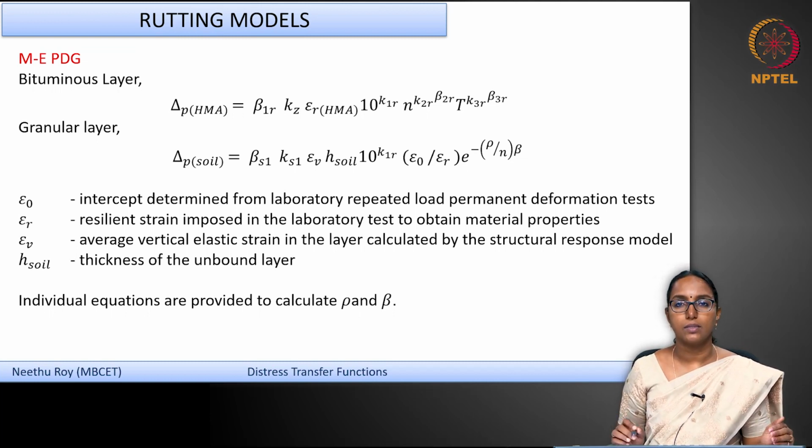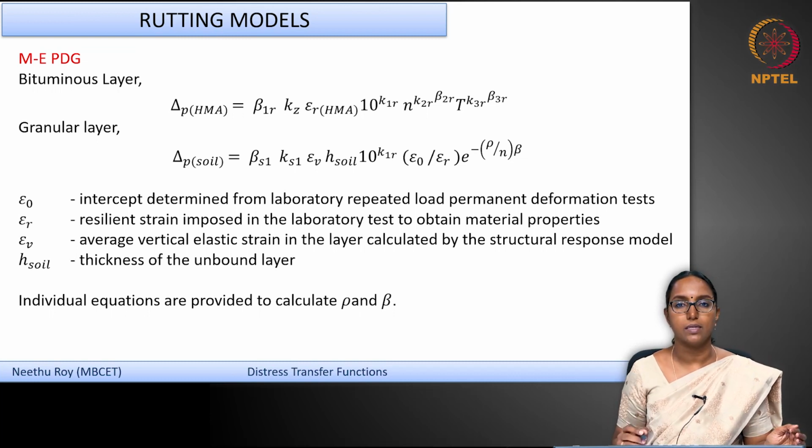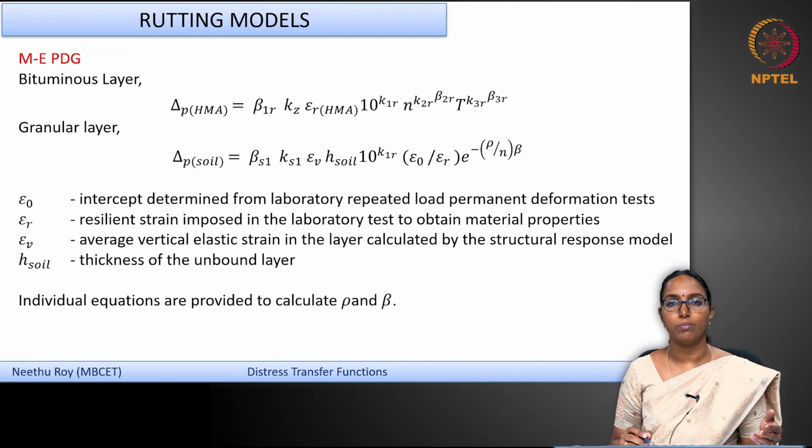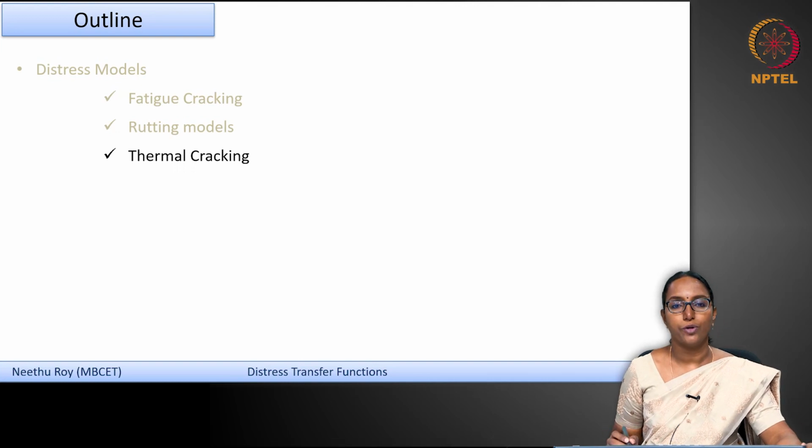So such distress equations can be again developed based on the studies that are conducted on the HMA mixtures in the laboratory and the extensive field studies that relate the number of load applications to the permanent deformations that you see in the field.